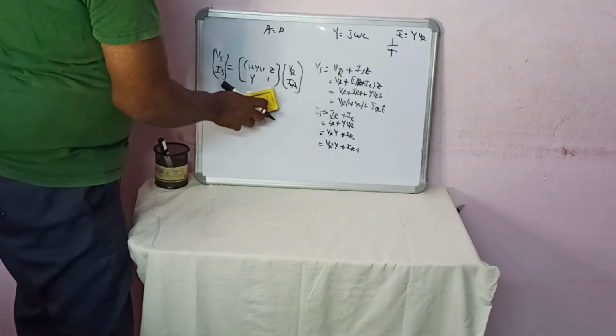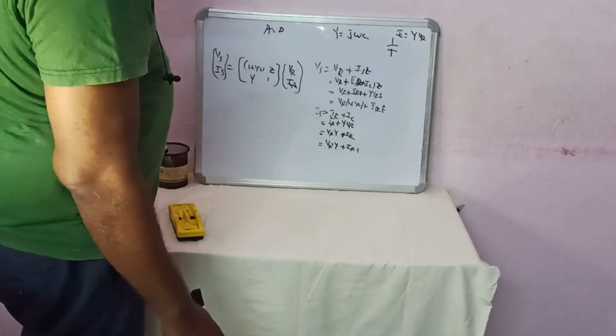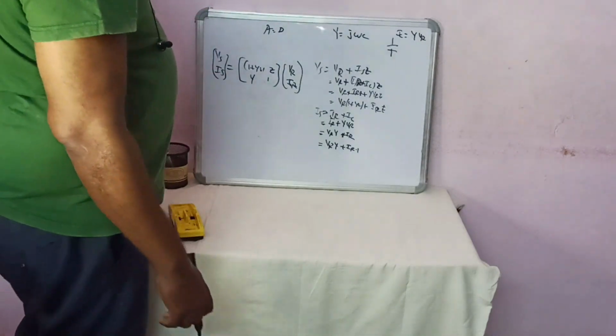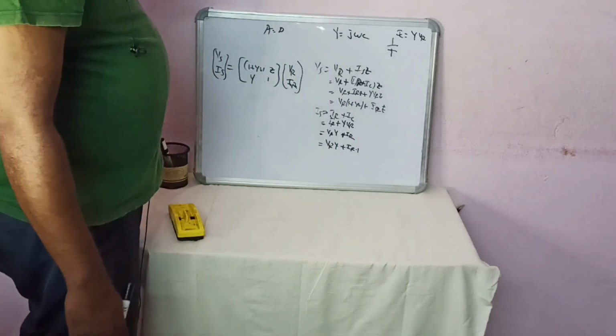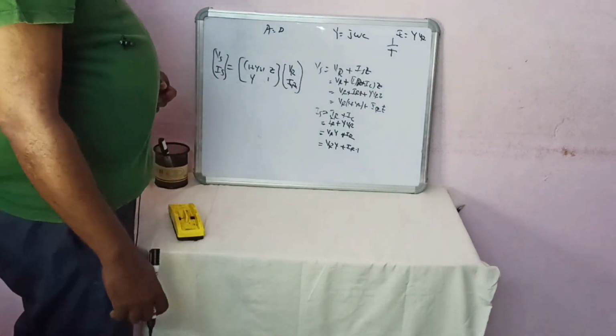This is defined in the form of a matrix. If the value of A is equal to D, the transmission line network should be symmetrical. On similar lines, if A is not equal to D, then it will not be a symmetrical transmission line.